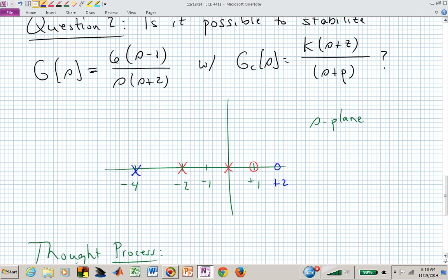We definitely don't want to make our infinity go to the right, do we? We didn't want that pole at positive infinity. Then it would just be flying into that 0 at +2, and it would always be unstable. Our infinity, in this case, is minus infinity. It's not plus j infinity or minus j infinity. Those have to occur in conjugate pairs if we're going to build this with a real system. So we located it at -4.